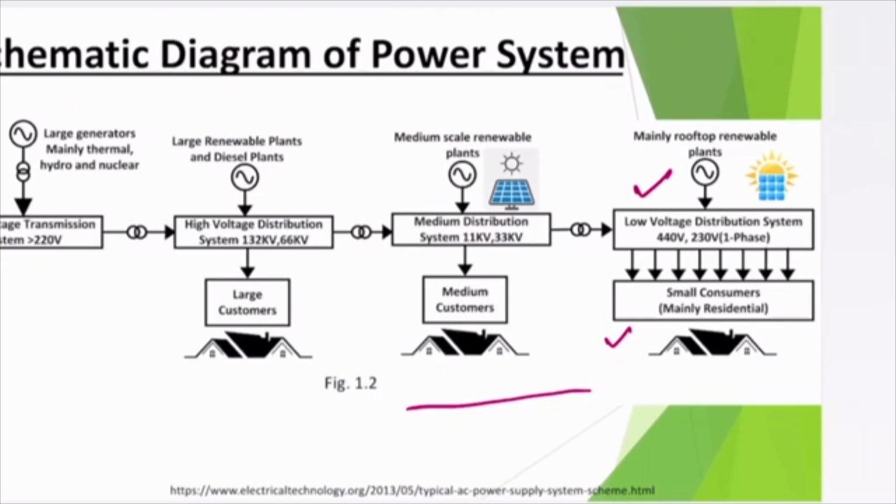And it's a very interesting part. This kind of integration of energy sources at different voltage levels not only enhances the efficiency of the network, but also significantly reduces the transmission and distribution losses, because the generating stations in the past used to be very far away, 100 to 500 miles away, but today the generating stations are partially available to you next door, so the transmission and distribution losses are significantly reduced.